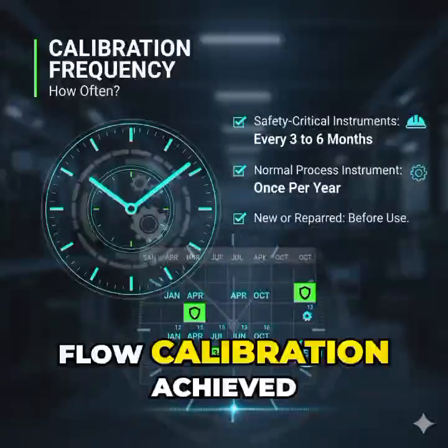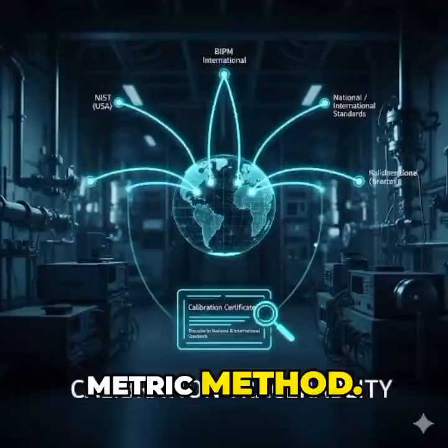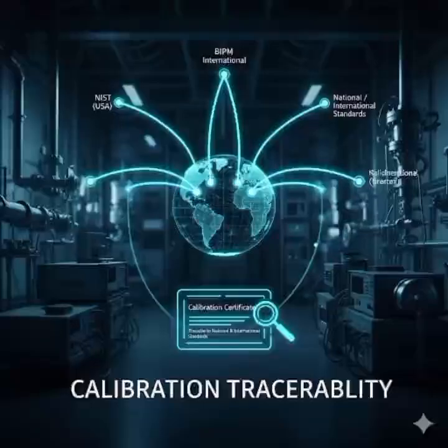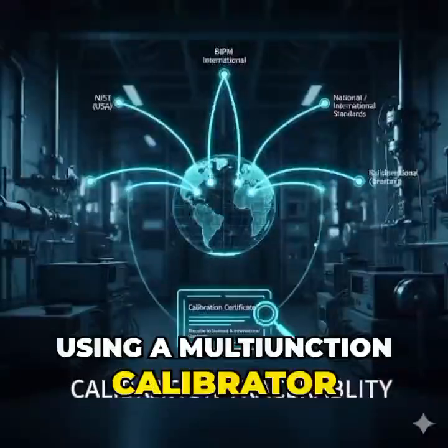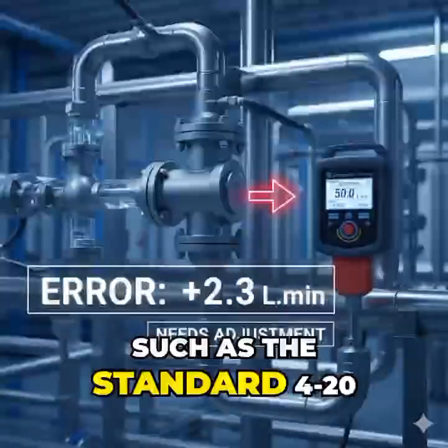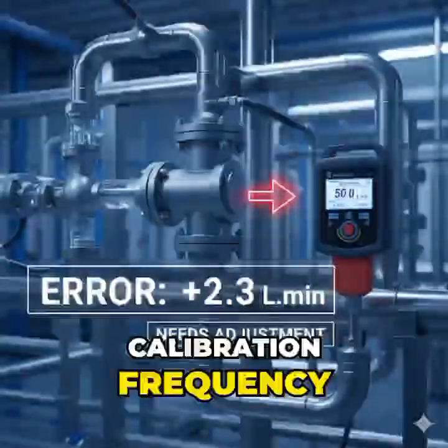Flow calibration, achieved using the master meter method or the gravimetric method. Level calibration, simulated with water columns, pressure head, or reference tanks. Electrical signal calibration, using a multifunction calibrator to source or measure voltage and current, such as the standard 4 to 20 milliamp signals.